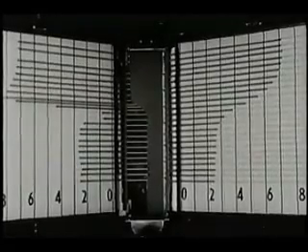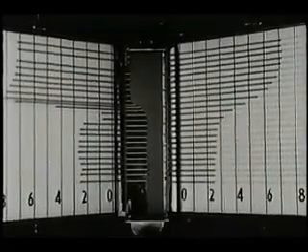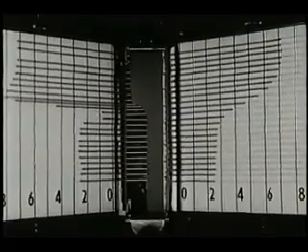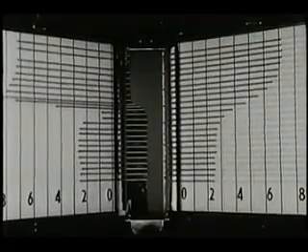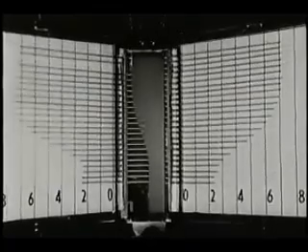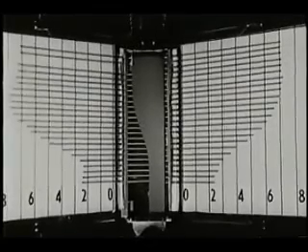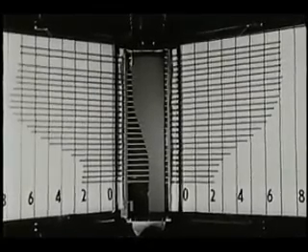The streamline curvature is now much less, and the normal pressure gradients which caused the distinctive peaks in the pressure distribution are reduced. The flow is more nearly one-dimensional, and the pressure distributions on the two walls are more nearly alike.